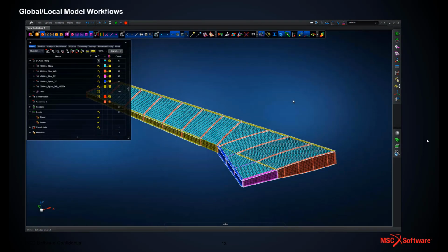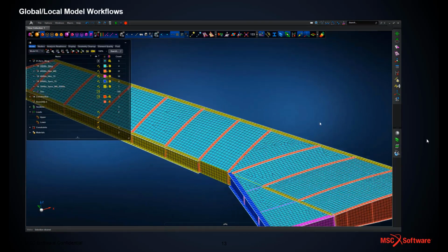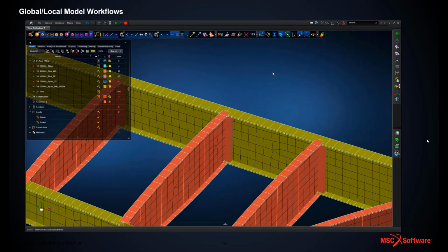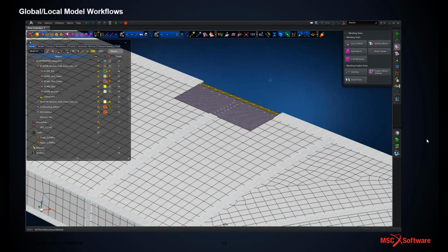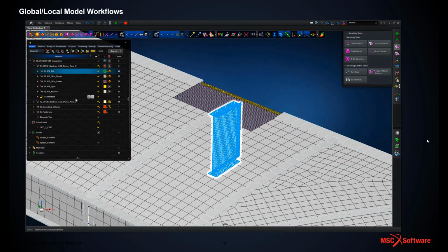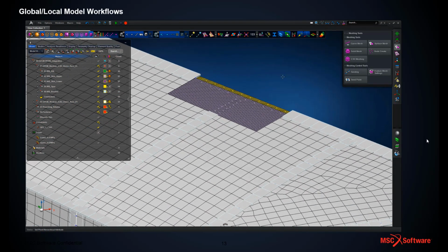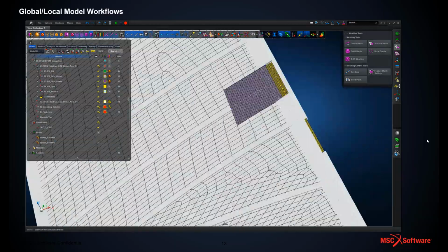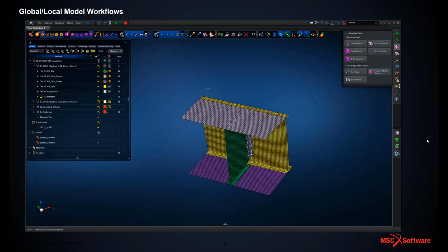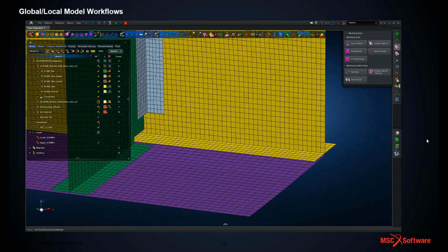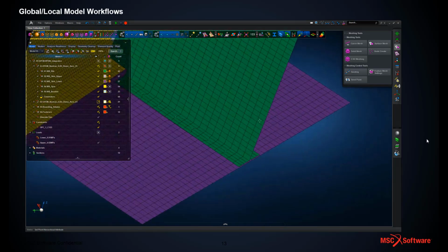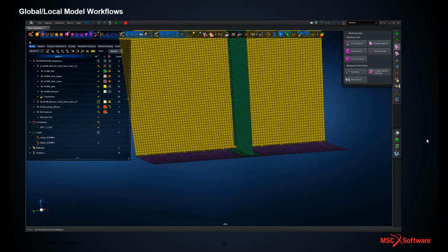Okay, so we're just going to again look at the screen recording. Here we have the same wing global FEM model read in that we looked at previously, just showing some of the topology at a rib to spar joint definition, and then we've read in the detailed region, and this has been developed in a manner similar to what we looked at with the previous screen recording. So we've got a newly meshed wing skin, rib and front spar. We've included some local detail, and we've modified some of the faceted or lofted surface geometry to give us cutouts at the rib to spar interface.